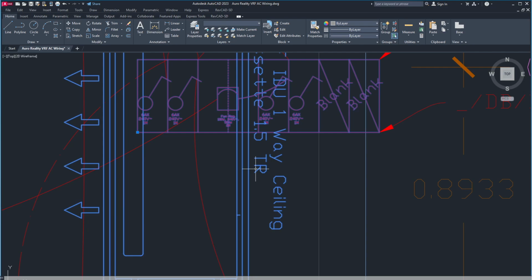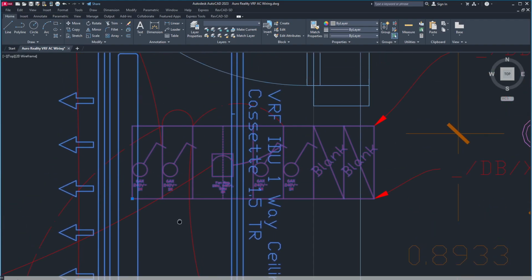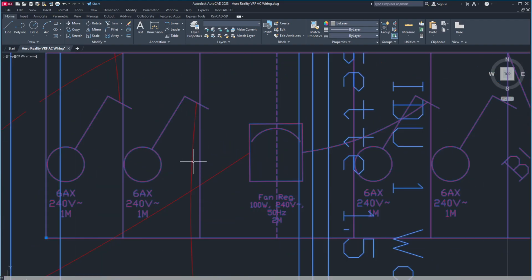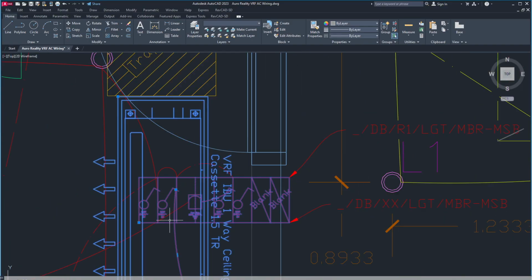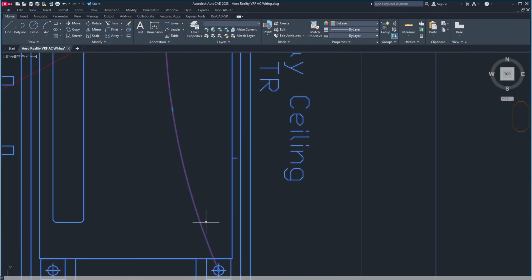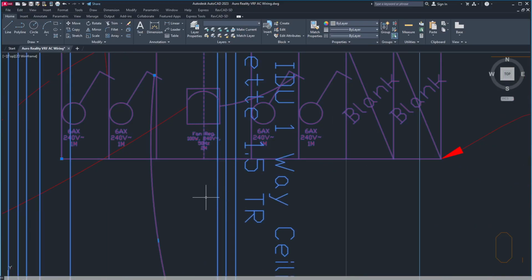This indoor unit has what in it? It has an evaporator. Then there is a throttle valve in it. There is one small throttle valve, one evaporator, and a fan. How much wattage will the fan draw? Hardly 60 watts or 80 watts. So that is the science behind why I have used a 6 ampere switch to control this indoor unit. This is a 1.5 TR unit.